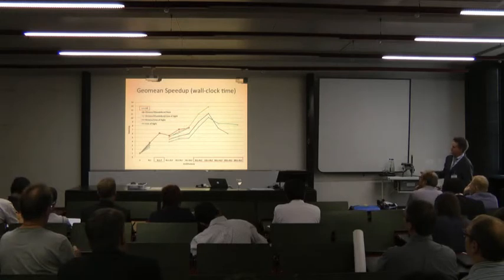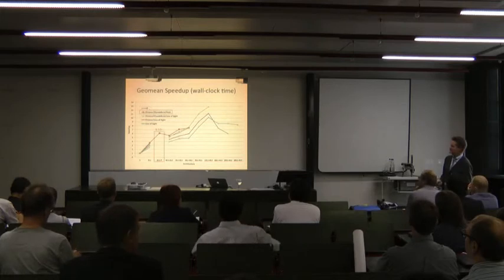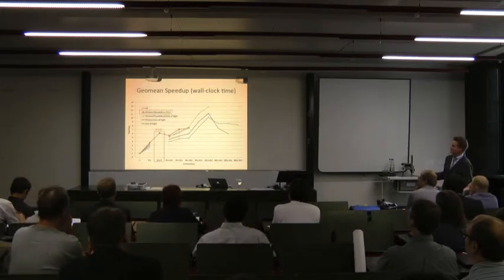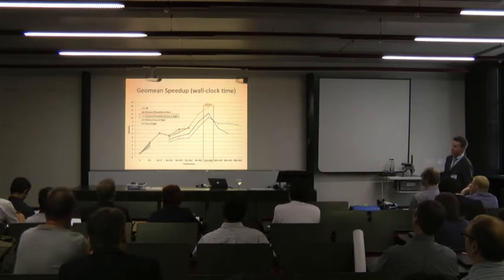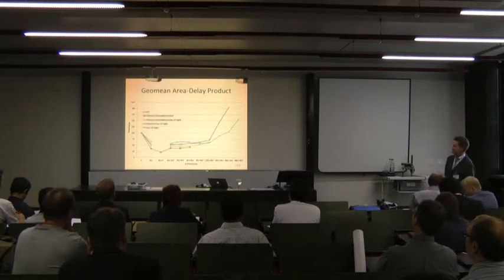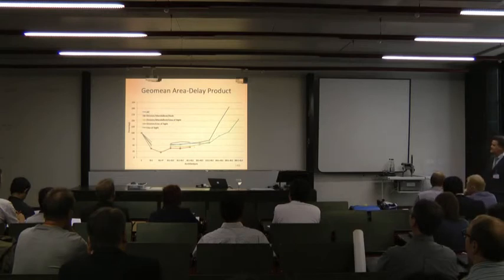Now, of course, as I said, not all architectures were relevant for all circuits. For division, Mandelbrot, and hash, 4 level 1 accelerators with loop pipelining inside gave a 6x speed-up. With 4 level 1 and 4 level 2, so 16 accelerators, 7.5x speed-up. The biggest gain we saw was for these circuits right here, about a 13x speed-up with 4 level 1 accelerators and 4 level 2 accelerators. We also looked at the area-delay product.